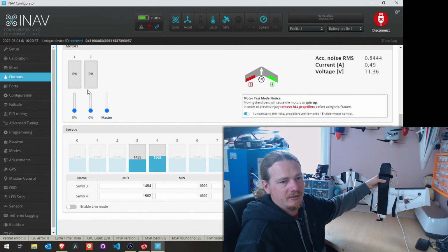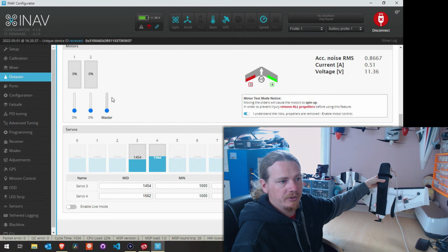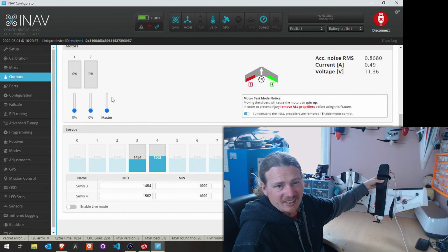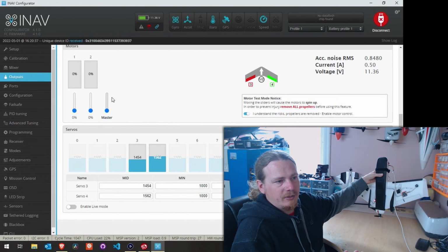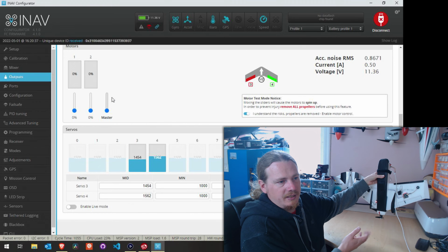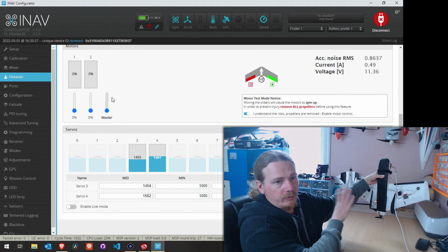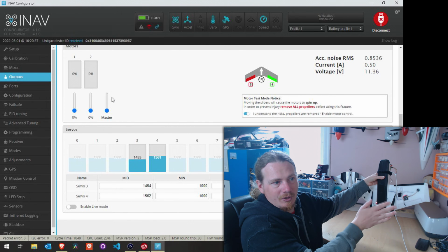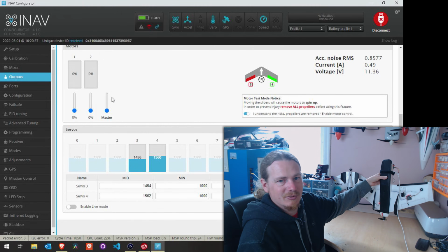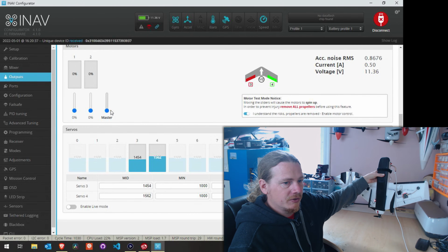And what we need to do is increase the throttle until we get to the buoyant point. Again, it could be slightly pushing up, but we basically want it so that the motor is providing enough thrust to take the whole weight of the plane. If we were to let go of it and it didn't want to fall over and cause all kinds of mayhem, it would just float there. What we're going to do is just raise the throttle.